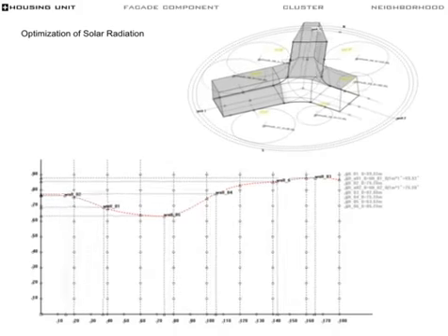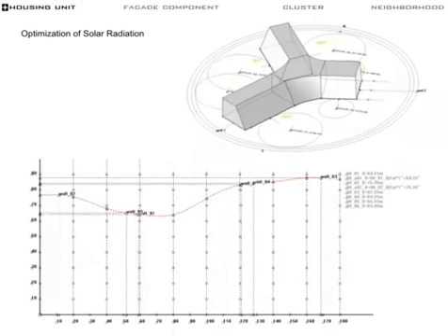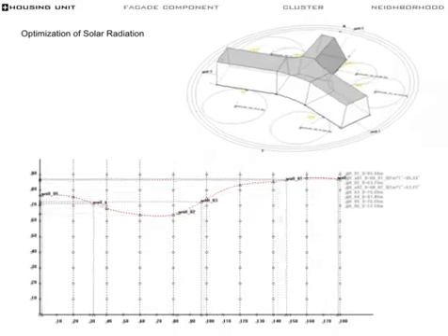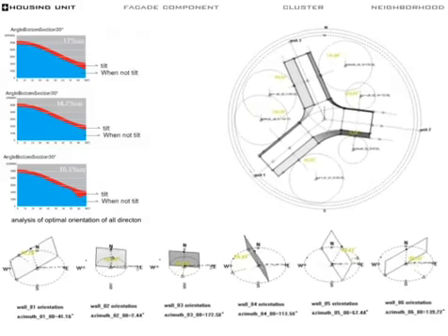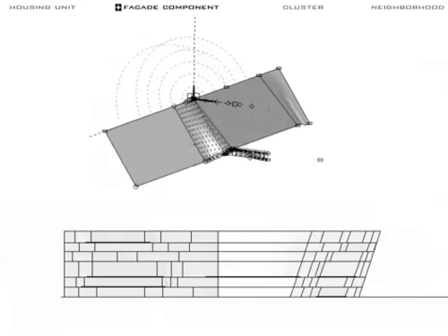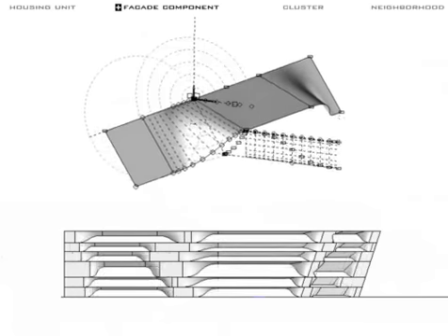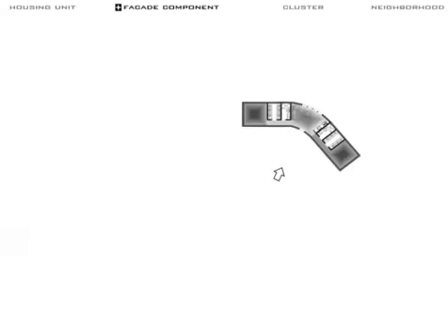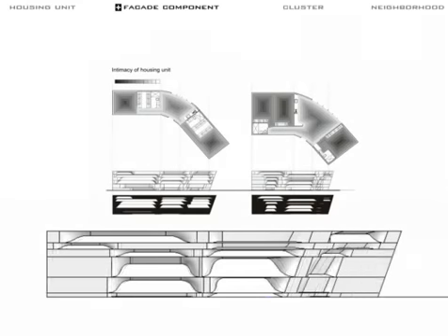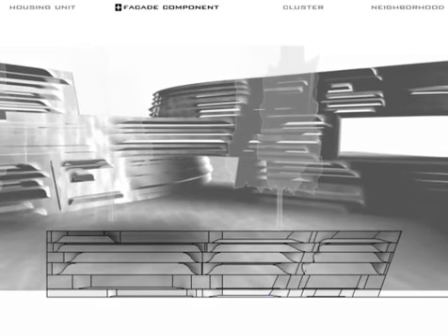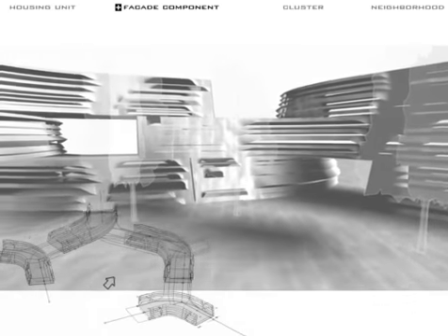The local inclination of unit facade is suggested by solar azimuth in order to acquire the optimal radiation. The facade is generated by different pitch sections due to its orientation. The envelope, while providing sufficient shading, suggests a differentiated level of intimacy which arises between the internal planning of the units and outdoor courtyard spaces. The openings of the shading device are calculated to shade either one single or multiple units.